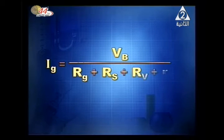And what about the current passing when we obtain the full scale deflection? IG equals VB over RG plus RS plus RV plus r. VB is the EMF of the cell, RG is the resistance of the galvanometer, RS is the value of the standard fixed resistor, RV is the chosen value of the variable resistor, and small r is the internal resistance of the cell.